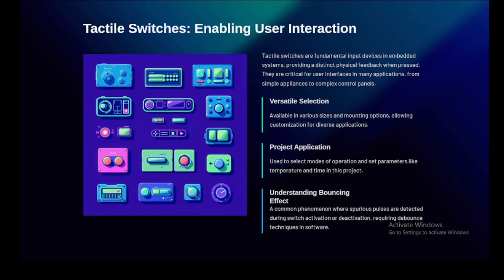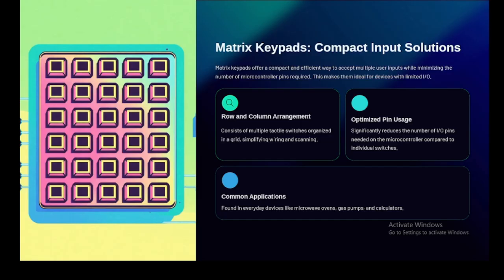Understanding the bouncing effect. It is a common phenomenon where spurious pulses are detected during switch activation or deactivation, requiring debounce techniques in software. Matrix keypads, compact input solutions.